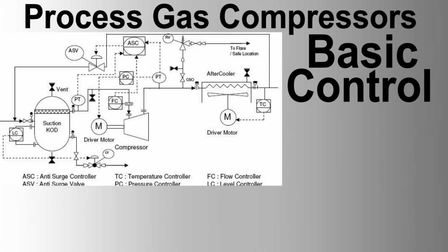Now, 4. Compressor control system, operational control and set points. A. Operational control. Automatic mode: the compressor operates based on predefined set points and process conditions. Manual mode: the operator can manually control the compressor speed and other parameters. Emergency stop: immediate shutdown in case of emergency.